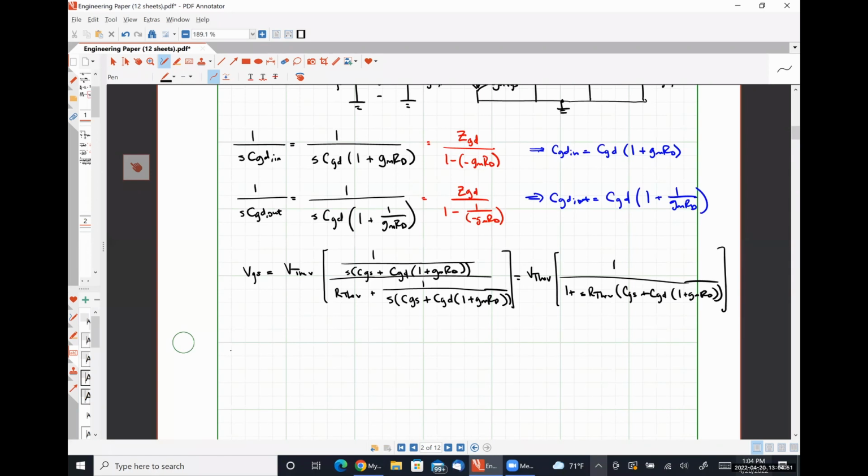So we're just looking for the relationship between those two nodes. What's connected to the nodes isn't particularly important, other than there being a feedback impedance between those two nodes that we're trying to split up. As we'll see with a common gate amplifier, there is no feedback impedance, so we can't use the Miller method. That's for some Friday.